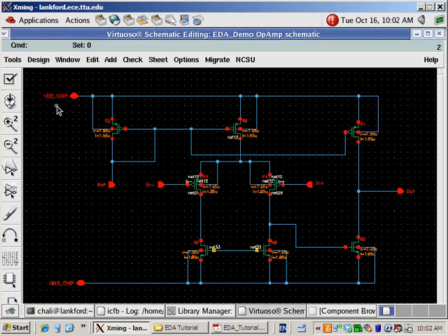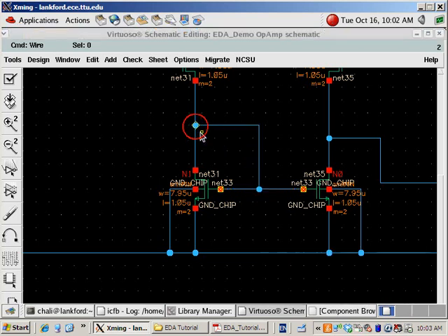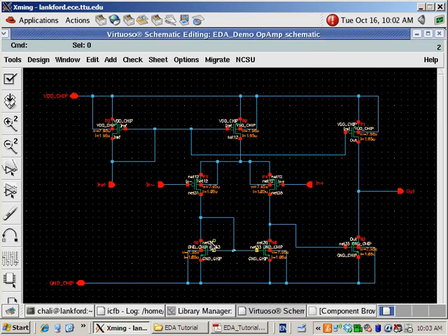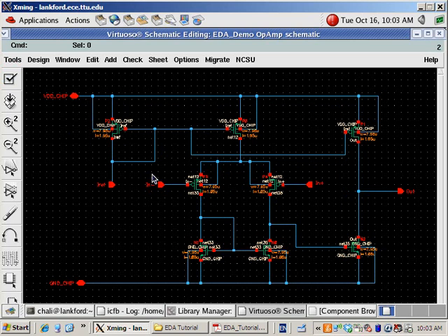Okay, all right, so this is my amplifier. And after I save it, it tells me there are two warnings, and the warning are already highlighted. So look at this, what's going on here? What's the problem? We are missing the current mirror, right? For differential pair, the load, we need to use diode connection for one side. Does this make sense? Okay, great. So now save it. Everything looks fine. Can you guys follow me on your computer?